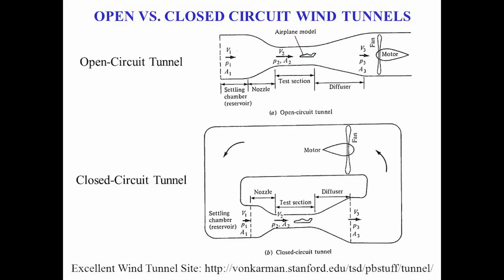And in present times, we have wind tunnels in all sorts of shapes, sizes, and capabilities. We can first classify whether a wind tunnel is open or closed circuit. Open means that the air is drawn externally, while a closed circuit one would keep recycling the air inside. You can also classify them into the range of speeds that they operate in, like low speed, subsonic, supersonic, or even hypersonic, and also by the size of the test section. And honestly, there's so many variants for different specific purposes that each wind tunnel design is really an engineering product of its own.